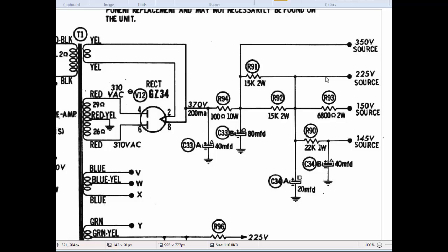Okay, this is actually the Pilot 232 amplifier that we had on the bench a while ago. This is the schematic for it, or one piece of the schematic. This is actually the power supply schematic, the part that ultimately provides voltages throughout the amplifier so that it operates properly. And different parts of the amplifier need different operating voltages, in other words, potential voltages, to be effective. So this power supply is not much different than the power supply I had up on my bench earlier, where I was creating the 9.7 volts.